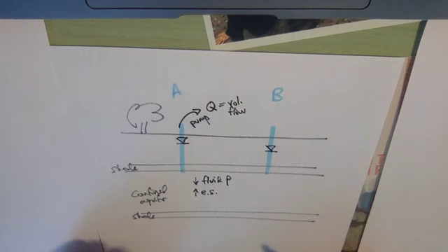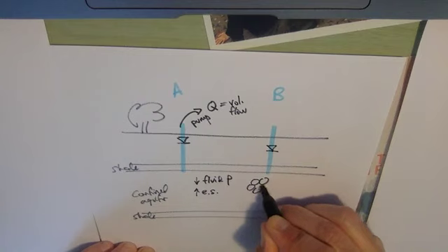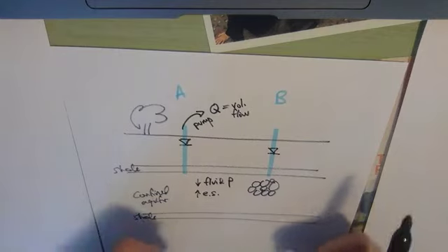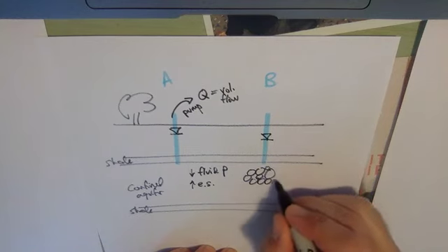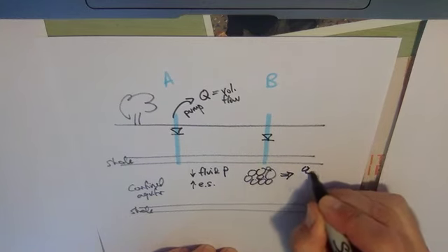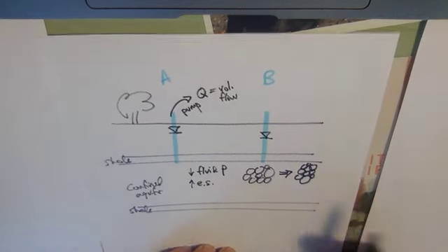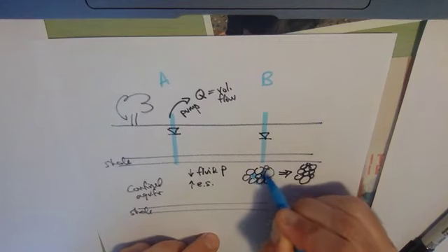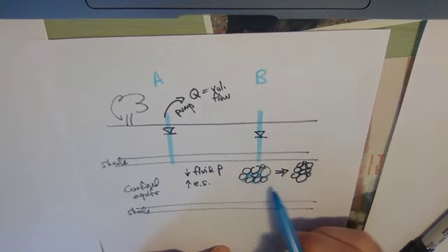And as a result, what happens is the grains, which we can imagine looking kind of like this if we zoomed in on them, are squeezed together under a tighter and tighter configuration. So they may start out looking like that, but they may end up looking like that. So the pore space, which is this space here in between the grains, has been reduced because the grains have been crushed in on themselves due to an increase in effective stress.